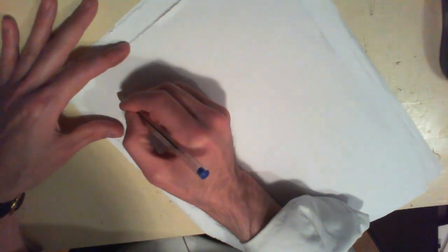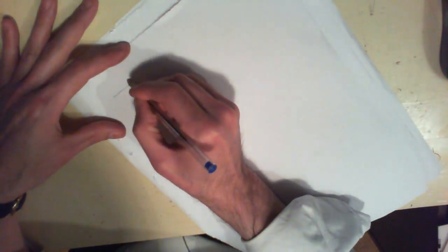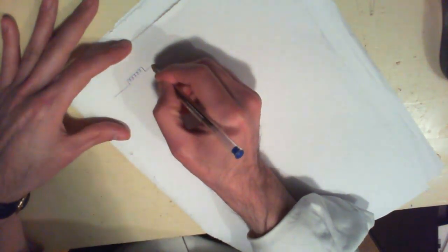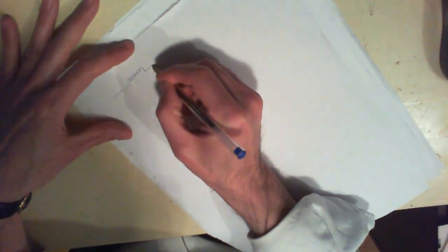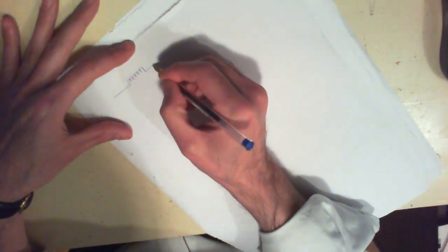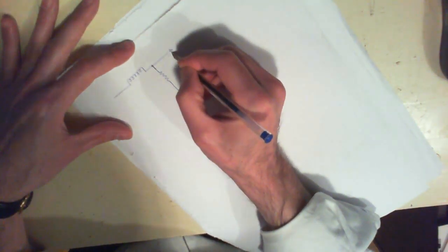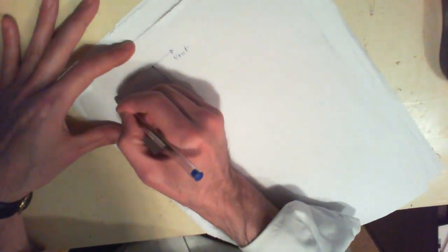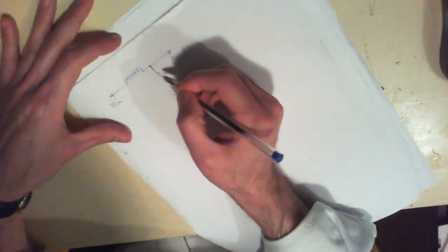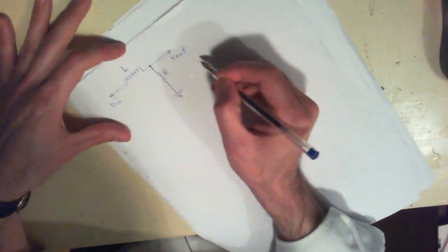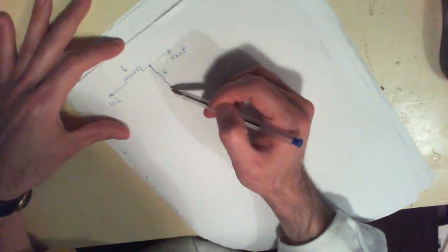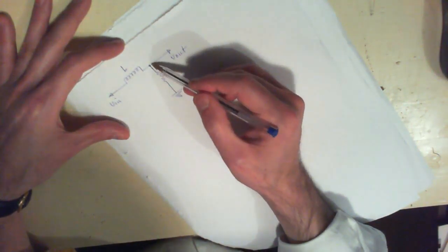The type of the RL circuit where you had an inductor over here, and then the inductor was connected to a resistor, and then the resistor goes to ground, and this is your V of out over here, and this over here is your V of in. So this is a resistor, this is an inductor, and the output voltage is the voltage across this resistor.